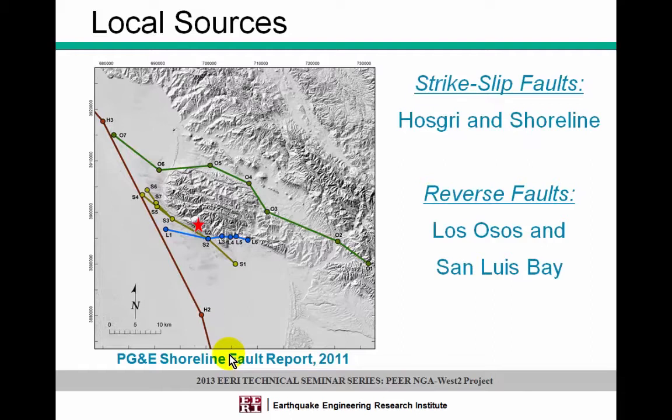So as we think back in ground motion models, either from the 2008 or the current models, the hanging wall motions tend to be larger than footwall sites. So that's one thing we need to consider.